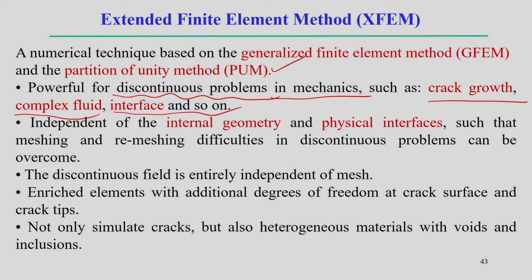It is basically independent of the internal geometry and physical interfaces, because remember it is a fixed domain, and we are implicitly tracking the interface. So, in that case we can use the extended finite element method, such that the meshing and remeshing difficulties in discontinuous problems are not there. Basically remeshing is not required in discontinuous problems. For example, there is a crack. How does the crack propagate, and how can we track it mathematically in a particular problem?